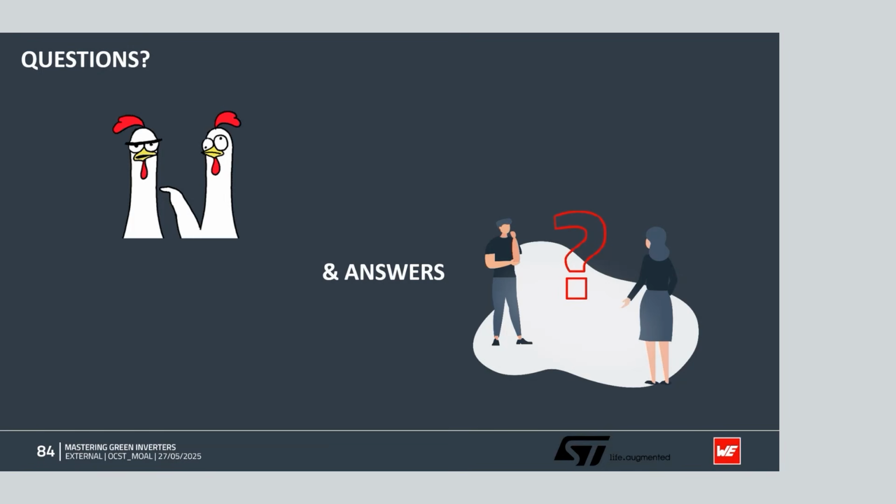What we have presented today was a complete system solution with this reference design for a heat pump application, which consisted of an active PFC, an inverter section for the compressor, and another inverter section for the fan, and also some driving possibilities for valves and other actuators. That was one solution example.